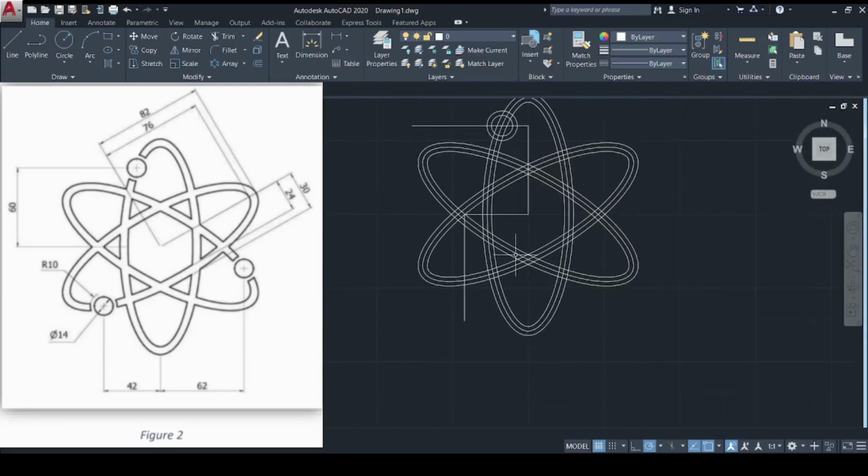Then another 62. Let's create a line that is 62, right? Yeah, 62. So, specify 62. Put it in the command line. Enter. And then, project. Enter.